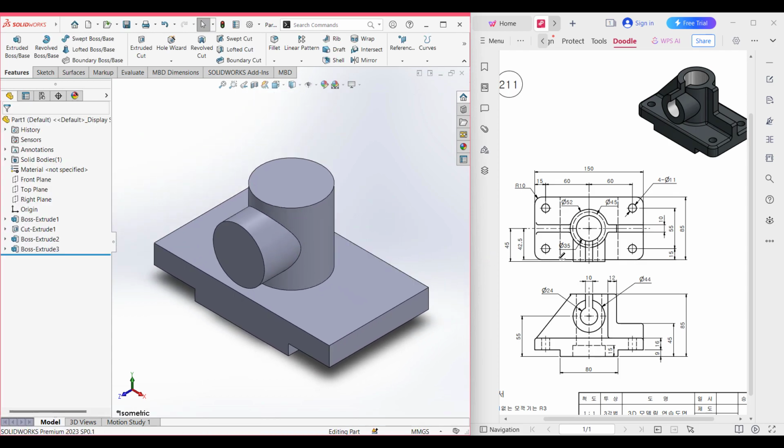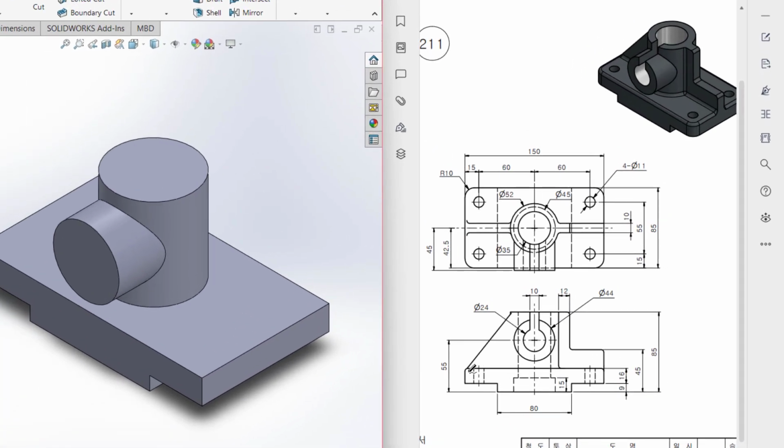Now let's go back to our sketch. In our sketch, we can see that we have an extra portion like this way. And for drawing this extra portion, first of all, I'll draw an inclined line from here to here. Then I'll extend a straight line, and this straight line has a dimension of, this is the diameter, so it has a dimension of 52, and as this is the length, so it has a total dimension of 52 plus 12 unit.